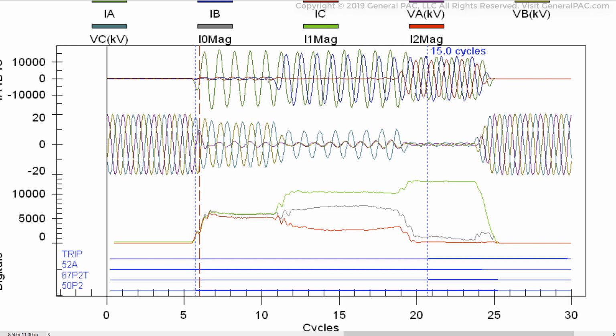And then towards when the fault became a two-line to ground fault, then we see a difference in positive, negative, and zero sequence currents, meaning that there are non-conforming values. There are three different magnitude quantities for positive, negative, and zero sequence current, right? And they continue to be. We know that this occurs for a two-line to ground fault.